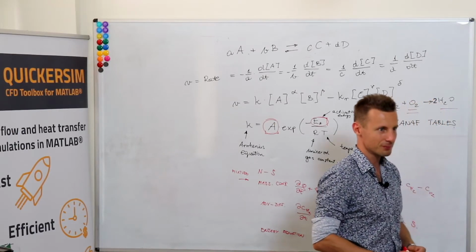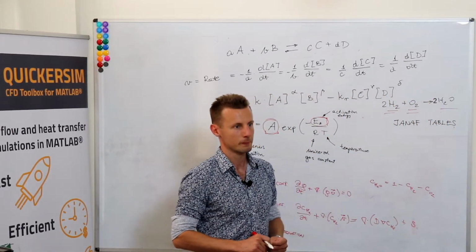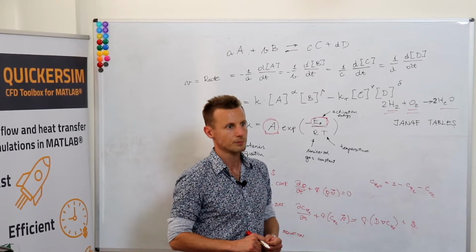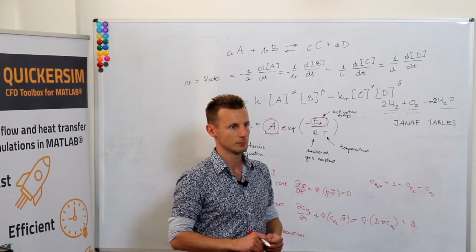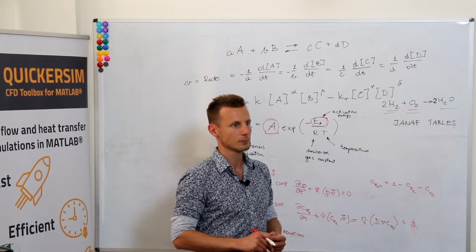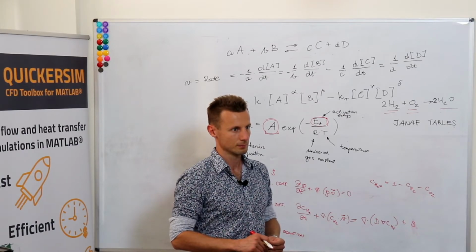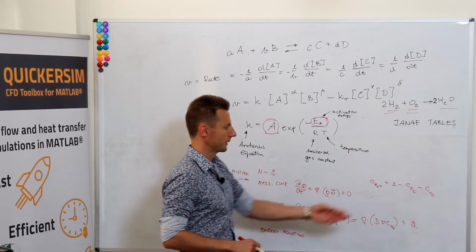Then when you're applying initial conditions, you can start with a simulation where you have oxygen throughout the whole domain, and you wonder why you have temperatures exceeding 10,000 Kelvin, for example. So be very wary of how these materials are sorted, what's the list, and what is the completion to one material. Saves a lot of time.